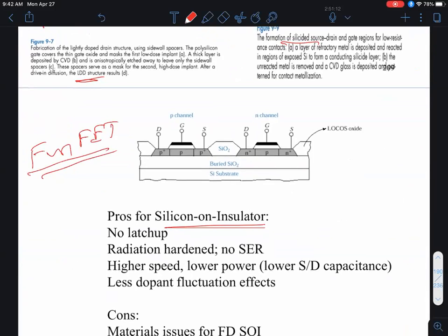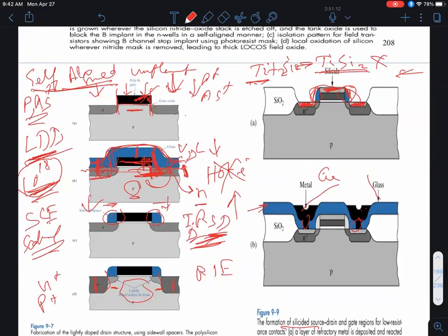The essential idea here is when you make your transistors, if you think about it, most of the silicon wafer has no electrical functionality, okay? A silicon wafer is going to be of the order of maybe 700 microns thick, while all your transistors are made in the top maybe 1 micron or so, okay? So the analogy that I use is, it's as if I build a skyscraper and I only allow people to live in the penthouse apartments, right?